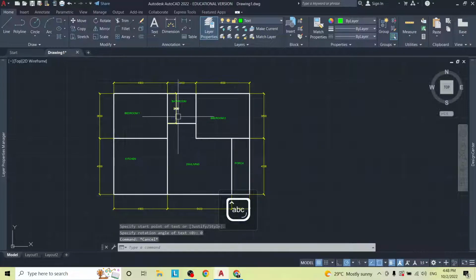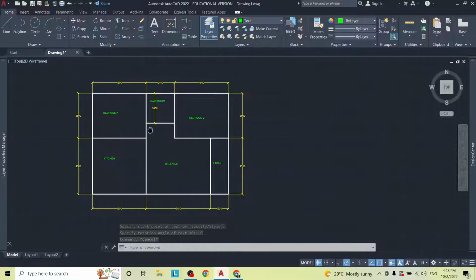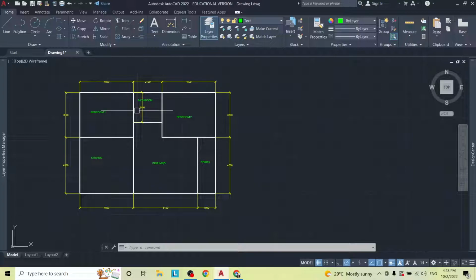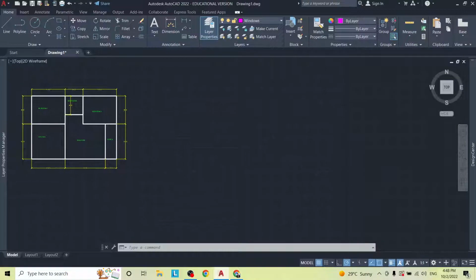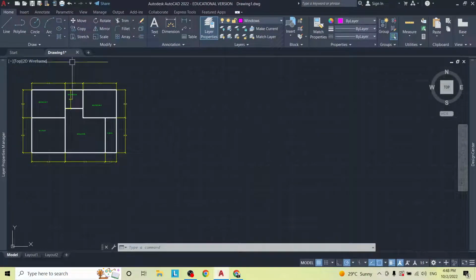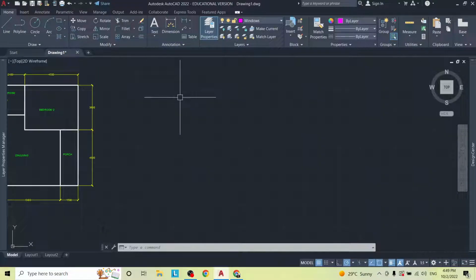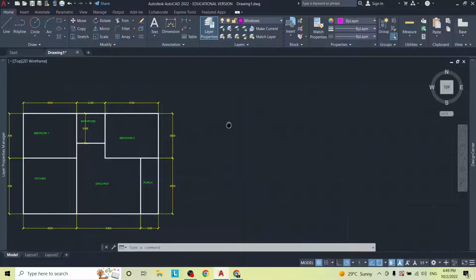So now we want to put in our doors and windows, and then we'll be good to go. This will be our sketch. All right. So doors and windows. Let's go to our layer for doors. Actually, let's do the windows first. So we're going to do something maybe new. We're going to create a block so that we can reuse these things over and over and over. So I'm going to create a block for our windows, our different types of windows.